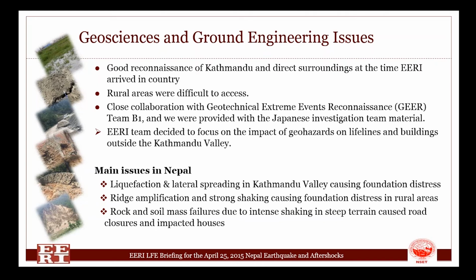The main issues in Nepal were around liquefaction and lateral spreading in the Kathmandu Valley itself that caused foundation distress. Out in the rural areas, more hilly terrain, we noted ridge amplification effects followed with strong shaking that caused building damage. In line with strong seismic shaking, rock and soil mass failures were observed on numerous instances as well.